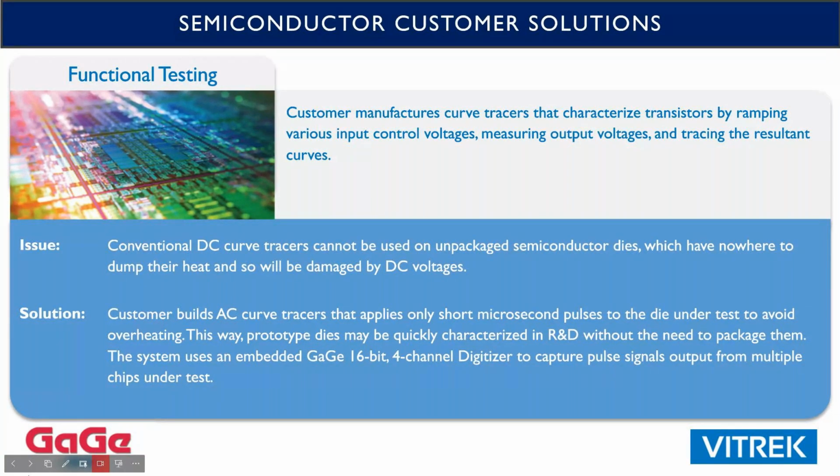So what they do then is, in manufacturing testing, they run the hard drive, and they read back signals from a known pattern written on the hard drive, and compare it to what the known pattern is. But at the same time, they can look at the raw read head voltage with the GaGe card and make sure that that's right. So they use it during development as well, to develop their disk reading algorithms, but also in production for quality assurance.